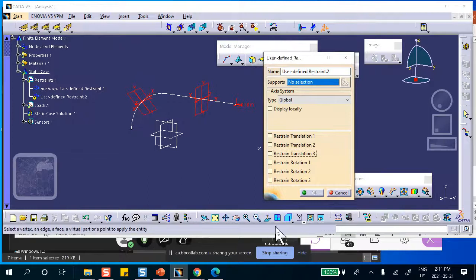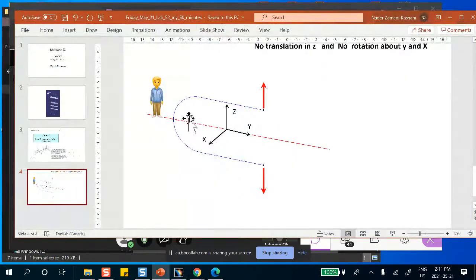Let me remind you that even if this was a solid object, and you created a cut here, and you put a surface slider, all that means is that the stuff in that cut that you made does not go up or down. So a surface slider or a roller is nothing fancy. It just specifies the displacement in the normal direction to be 0.